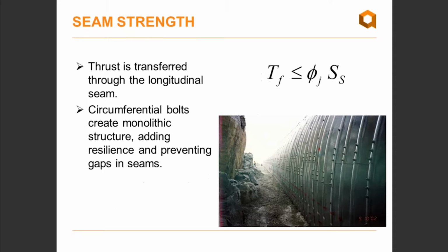And last but not least, all bolted structures require a seam strength check to ensure that the factored thrusts do not exceed the factored resistance of the longitudinal bolted seam.